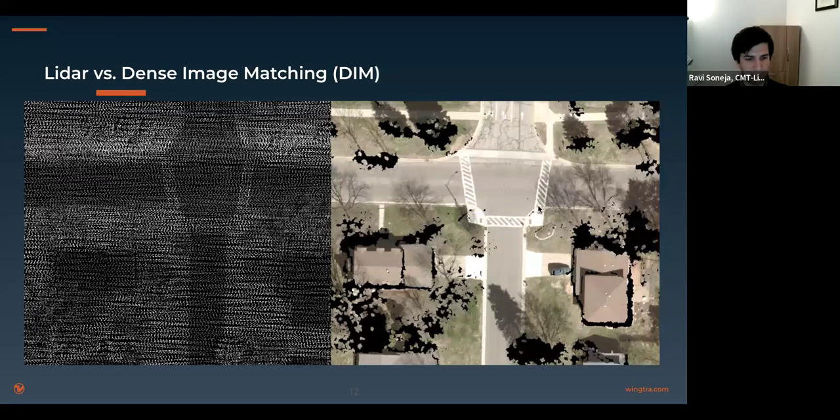Sure. If I had to break that down, we broke up setting the actual targeting and putting the PK nails in the ground and then coming back and observing everything, collecting check shots. That's probably going to be somewhere in the range of about 8 to 12 hours worth of time, realistically. As far as the actual acquisition, I think you're probably in the 2 to 4 hour range somewhere.